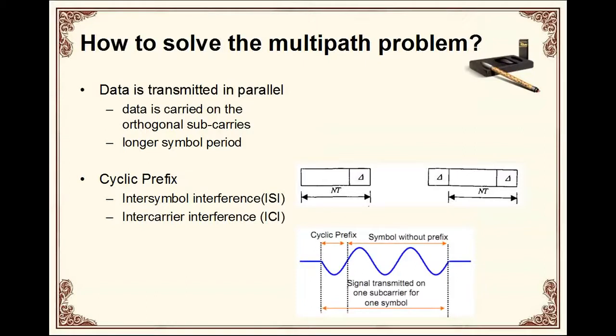Because of the use of orthogonality, there is a half overlap of every adjacent subchannel. Thus, the spectral efficiency is nearly double that of a single-carrier transmission system. When a certain frequency of the transmission channel experiences fading, only the subcarrier at that frequency will be affected. Parallel transmission ensures a low data rate per subcarrier, which diminishes the probability of intersymbol interference.